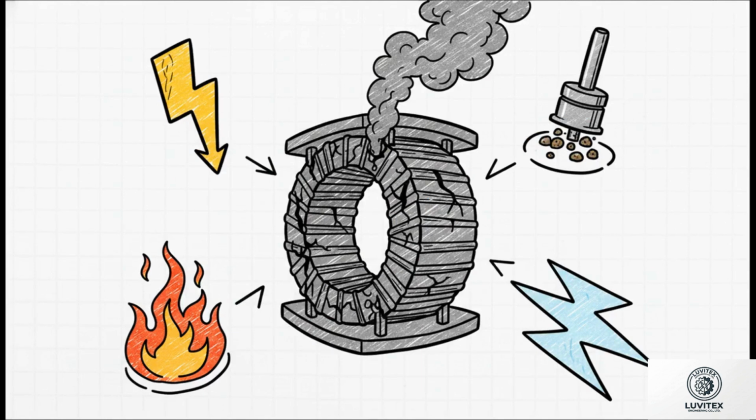Just think about undervoltage, right? If the magnetic field is too weak to fully pull the plunger all the way in, the valve continuously draws that massive 5x surge until the insulation inside literally melts. The exact same disaster happens if even a tiny piece of dirt jams the plunger so it can't seat fully. Add in things like rapid cycling, which builds up trapped heat with no time to dissipate, or electrical spikes from nearby heavy machinery frying the insulation, and you can easily see why these normally robust components end up failing.